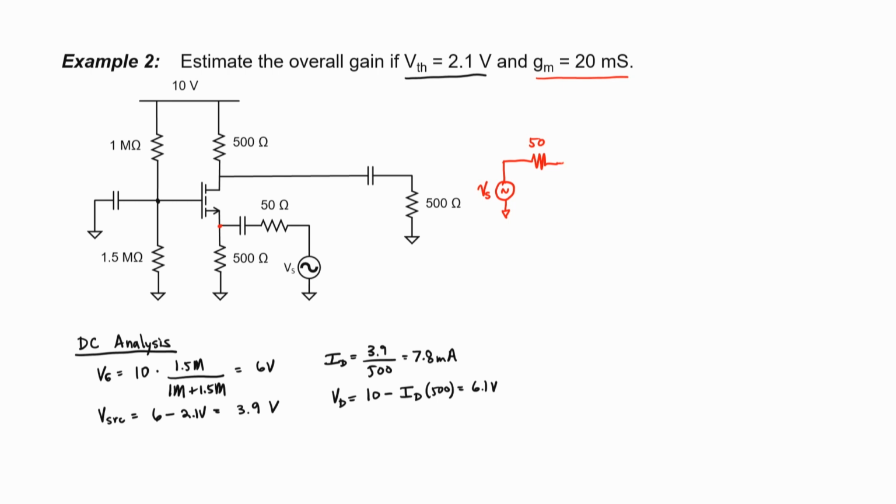At this point, we have 2 resistances. We have a 500 ohm resistance looking down, and we have a little resistance looking up, given by 1 over our transconductance. If I take 1 and divide it by our transconductance, I'll wind up with 50 ohms. Lower transconductance, a higher effective resistance. We can add that resistance to our equivalent circuit and move on to the gain segment.